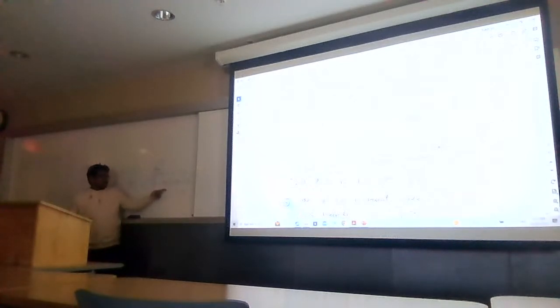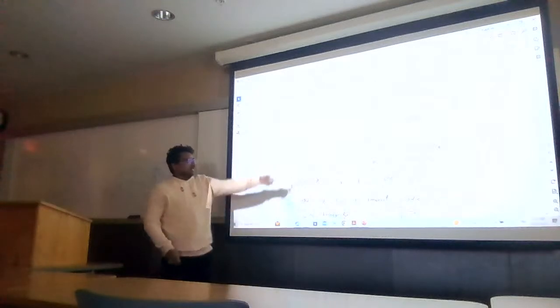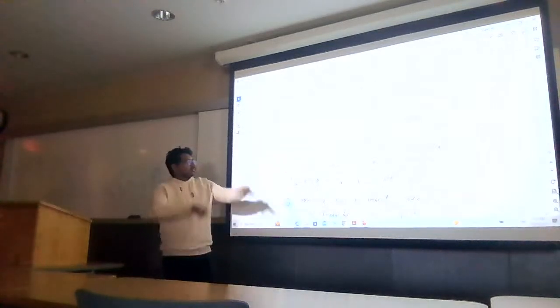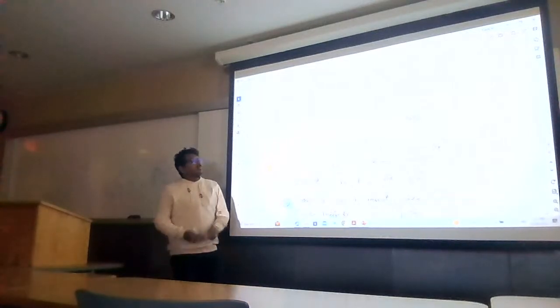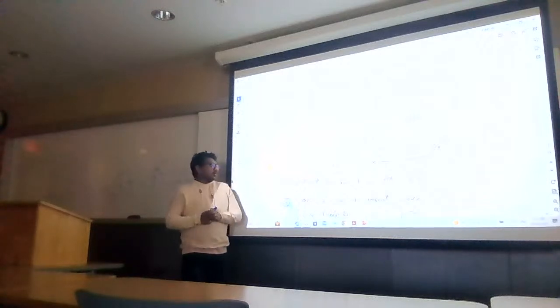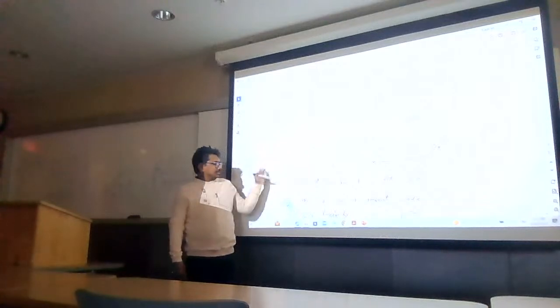If it breaks this condition, then this transistor will go into the triode region. The curve I discussed, it will not be in saturation, then it will not work. So there is some limitation. I cannot increase this resistance too much. Along with that, if you look at the formula of GM, there is also some limitation. We cannot expect a huge gain from this circuit. The typical gain of a common source amplifier is 5 to 10 dB. Here I explained that we can increase RD and ID, but there is some limitation.